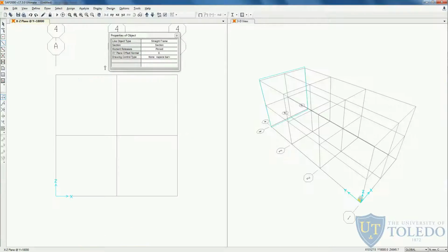This is the easiest way, but you can also come here and draw the nodes by itself before creating the elements. However, to create elements since the beginning is better because it will create the elements and the nodes. So let's do that. So 1, 2, and then 2, 3, and 3, 4. From here, we can create basically from any type we want.